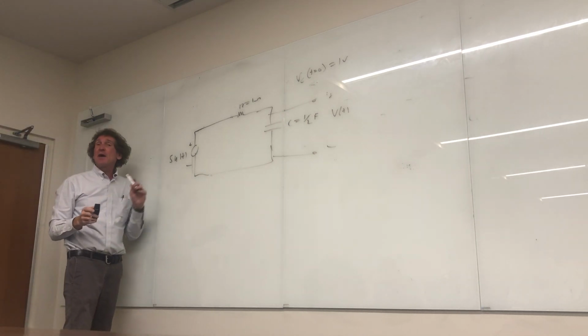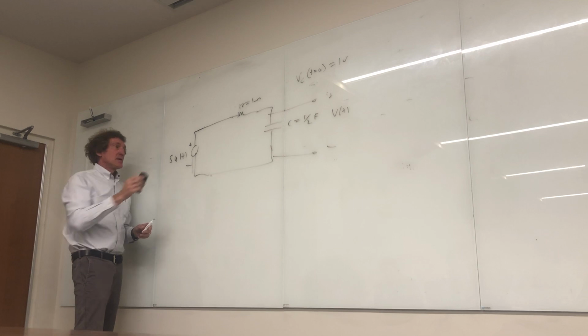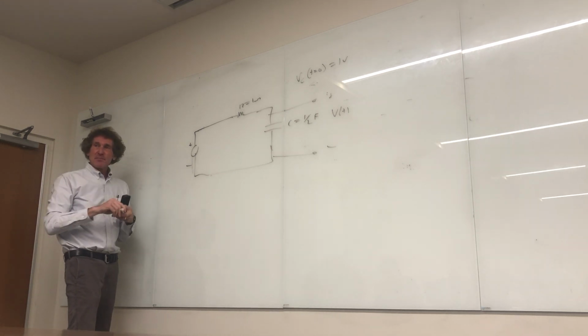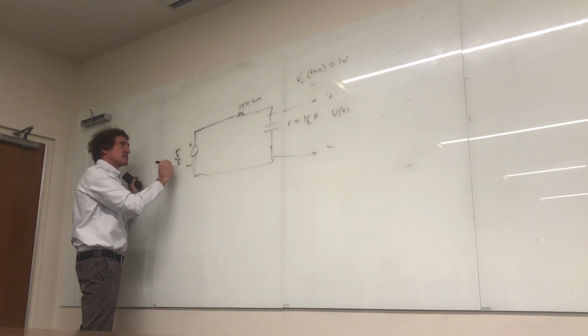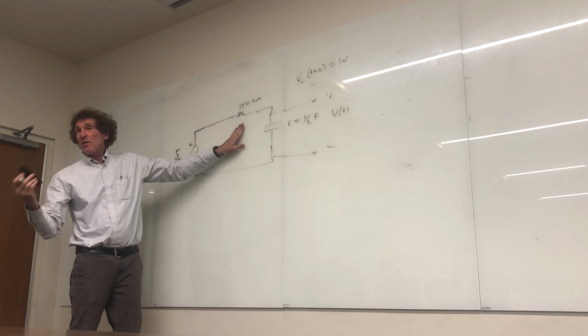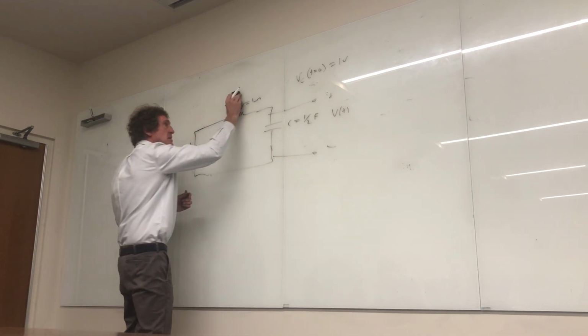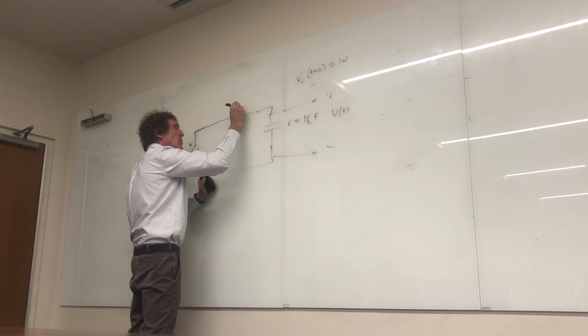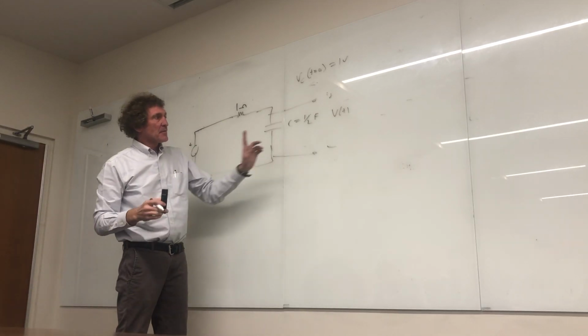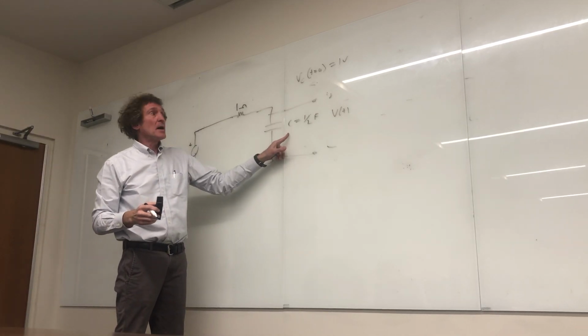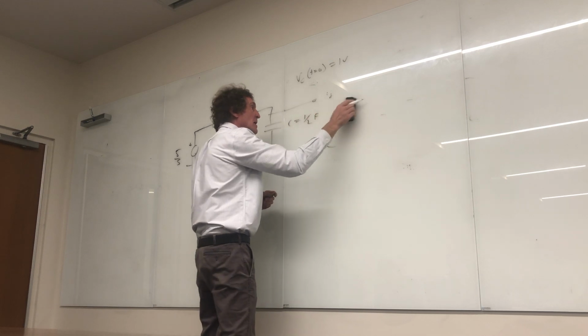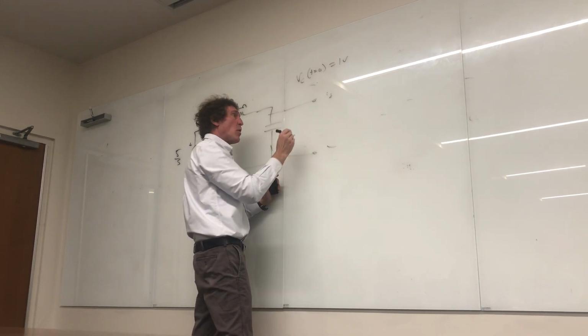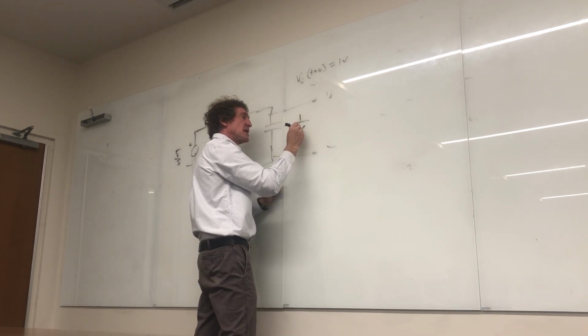So this becomes 5 over s, correct? Because I don't want to have to rush through this all the time. 5 over S. R is just R, right? It's 1 ohm, period. This is the impedance domain, so leave it as 1 ohm. Now this becomes what? Think about what it becomes. This is going to be 1 over SC, right?